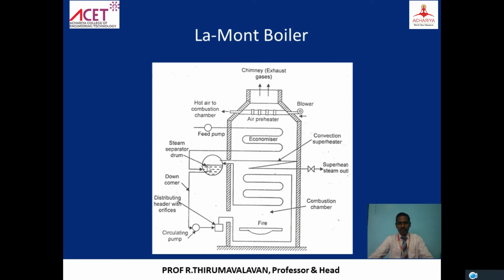And again, if you want to increase efficiency, from the feed pump, the water is coming to the economizer, where that water is preheated. That water is also coming to the boiler drum. From the feed pump it comes to the drum through the economizer. The economizer is a device which heats the inlet water, taking the heat from the flue gas.